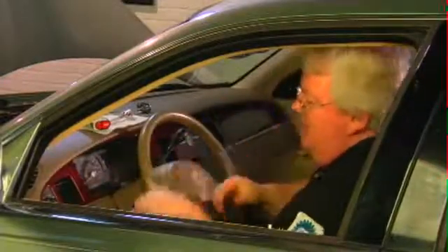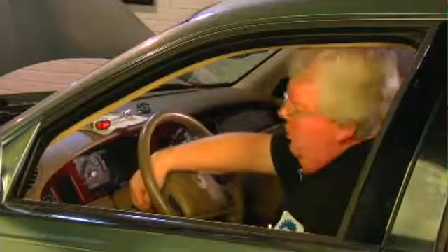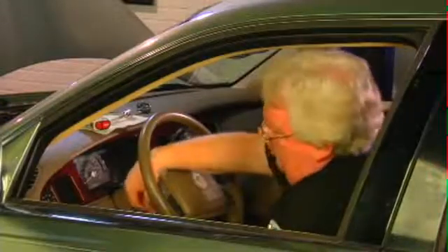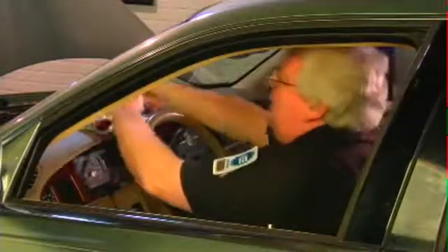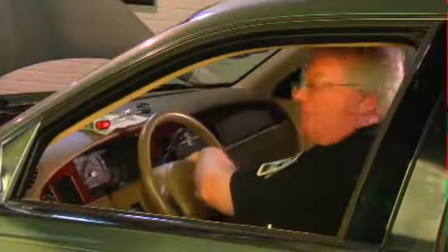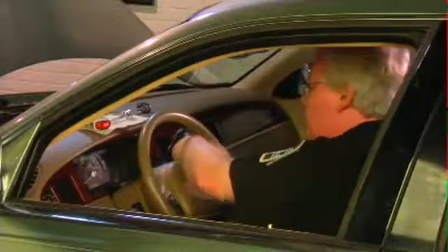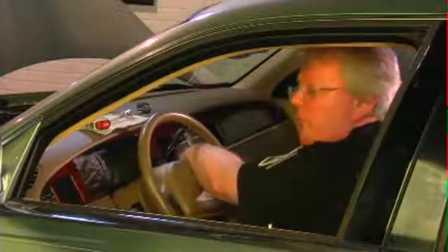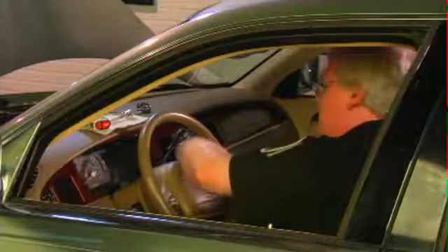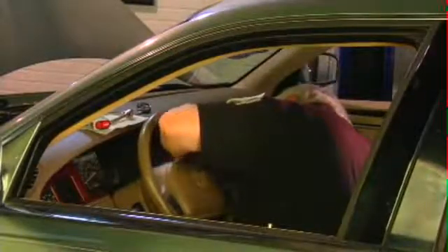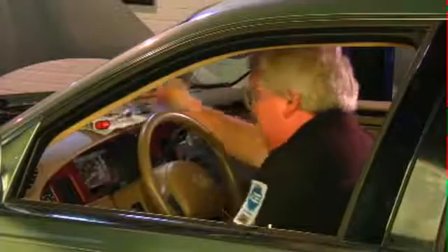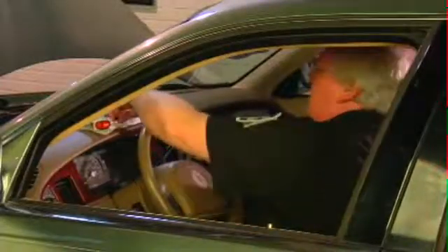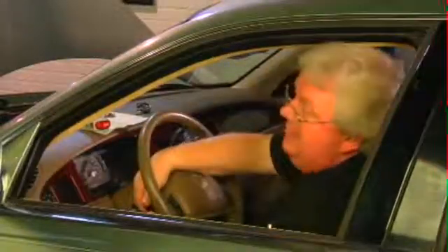We've waited, we took the battery cable off already, so we're going to do this by feel here. We're going to pull off a little covers for the airbag screws, and then we'll get busy taking that airbag out and talk about steering wheel removal. There we go. Now, get my little 10 millimeter, 8 millimeter.